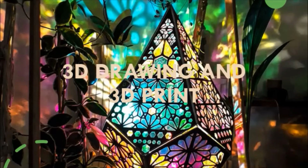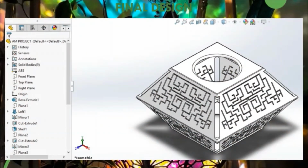For this slide, I would present about the drawing product and 3D print, which is the lampshade. As you can see, the lampshade design was created by using SolidWorks software. To complete this design, mostly I use the loft feature in order to achieve a specific height. For the angle, I use a 60-degree angle for a better look when applied for 3D printing.